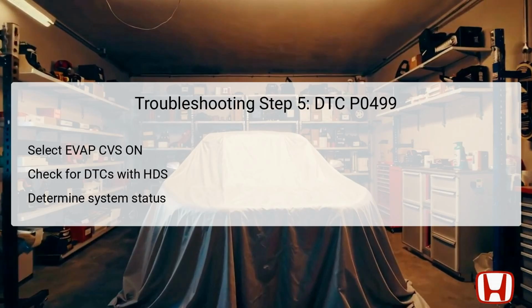If the ECM or PCM was newly updated, plan to substitute it with a known good module if the faults persist. Alternatively, if the DTC does not show up again, you will move forward with your final evaluations, establishing if the previous repairs were effective.